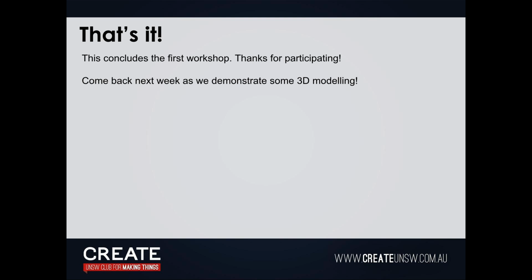Now, in this case, what we do is something we can call assemble, or you can do joint. We'll just do joint. Component 1. You select which to join where. And then component 2, we want to join it on this corner, right? Oh, I might have messed that up a bit. You can flip it.